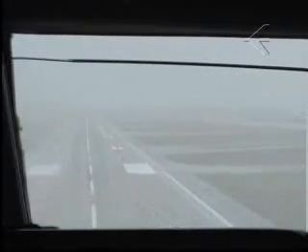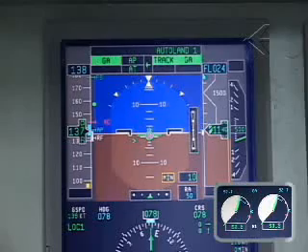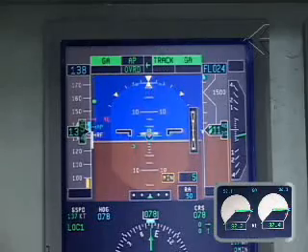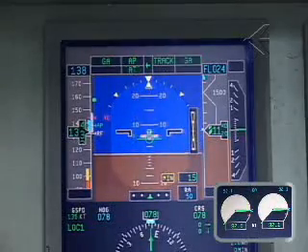Approaching the decision height, the pilot flying starts to look for visual references. He should come to this altitude prepared for a go-around. In CAT 3A, Autoland 1, the visual condition required at decision height is that there should be references that confirm that the aircraft is over the touchdown zone. Go-around is mandatory if no visual reference is confirmed or a failure occurs.